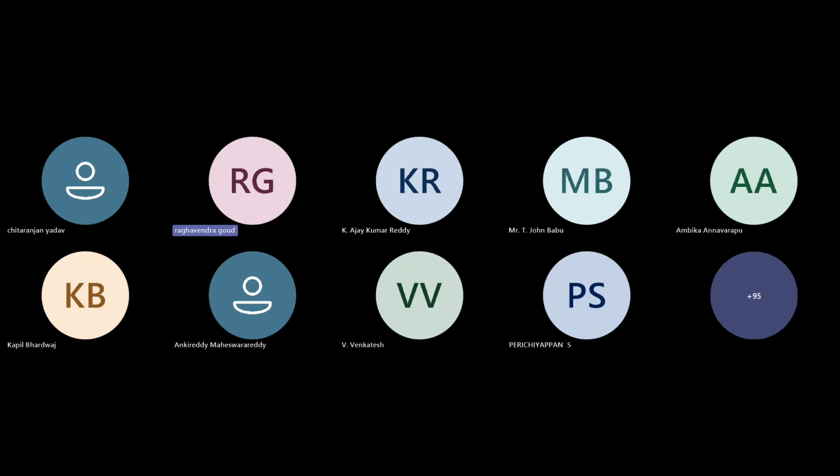Okay, sir, what are the different kinds of work we can do on that machine? Whatever setup I developed at our institute, sir, you can use this setup to print. I can tell you the list of materials which can be used in this setup, but I cannot tell you the application and other details. It's purely connected to your objectives. My setup can be used to extrude paste type material, powder form of polymer, granule form of polymer, sheet form of polymer, or polymer composites, hydrogels.